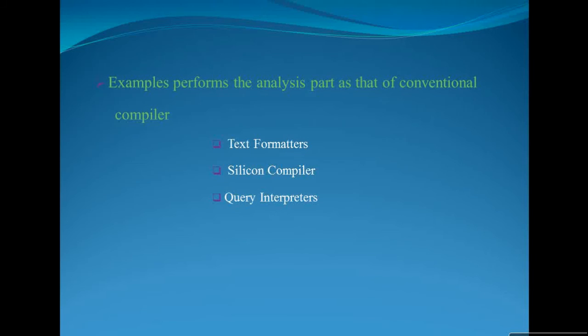So next is the silicon compiler. A silicon compiler takes a source language as input, but the variables in the input represent not locations in memory but logical signals, that is, zeros and ones in a switching circuit. The output, the circuit design, will be in appropriate languages. So it represents the input not as locations of memory but as logical signals of zeros and ones.